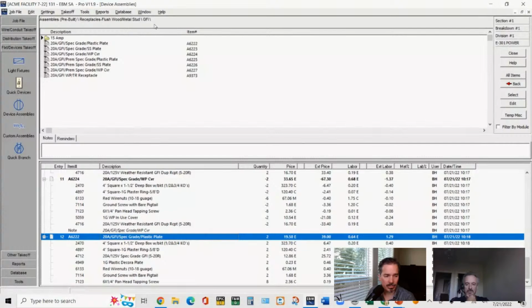Sometimes I get people that say, well, you know, a lot of the time we don't get drawings. What should I do? Well, that's where you use the design part. You actually place the symbols on the drawing, do your layout on the prints. I mean, you have to have some kind of a print. You have to have at least an outline of the building, and then you can actually put the symbols on the drawing. You can run your feeders. You can take off all of the same things you would need to if you didn't have an electrical layout.